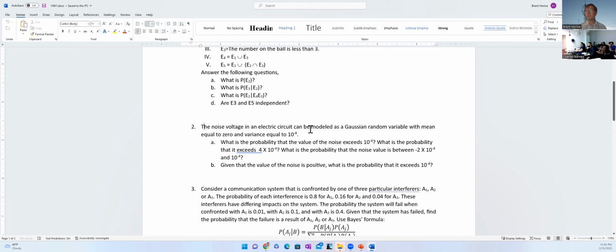Where this is the noise, if it's 0 mean, what's the probability that it exceeds that? So we're going to integrate from this value up to infinity, and look at the area under the tail of the curve. These different aspects here are really just setting up different limits, and you use the Q function and look it up in the table in the PowerPoint or PDF that I uploaded, and that should get you the answers on all these homeworks, as in the test.